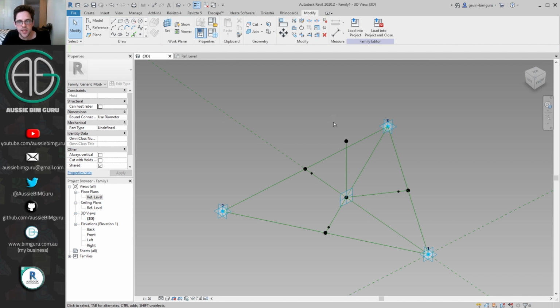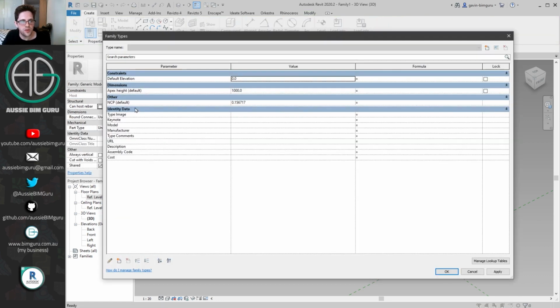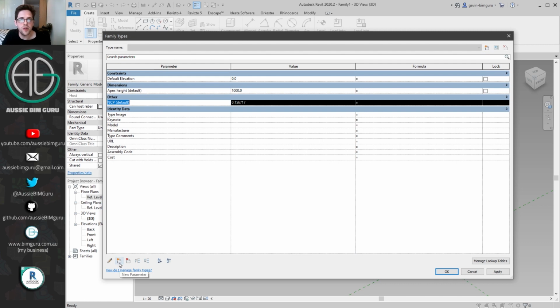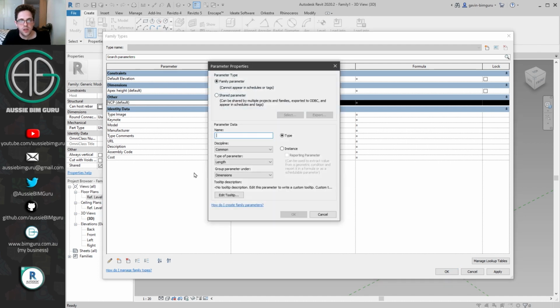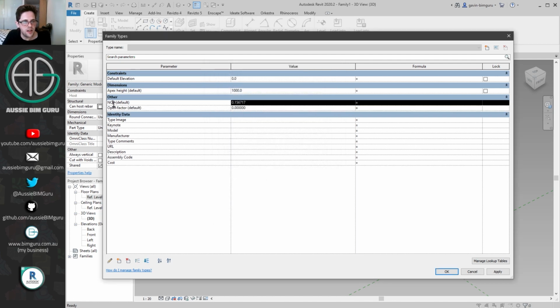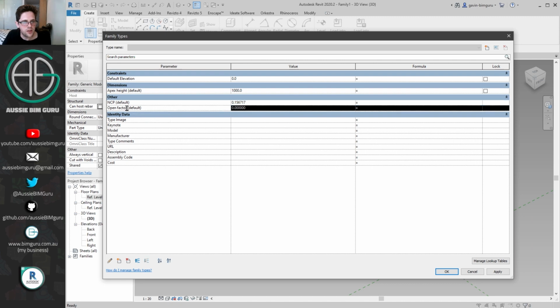Now the first thing we might do is actually just establish the formula that controls this inset and this offset. So what we're going to need for this is a number that's going to control that relationship. And this will also be the number that we're going to use to control the aperture of the panel using computational software. I'm going to make a new parameter, and I'm just going to call this the open factor of the panel. So how open is that panel? I'm going to make it instance-based, and I'm going to make it a number. Now in this case, I'm going to say that the normalized curve parameter is obviously going to be equal between 0 and 1, but like I said, I never want to quite fully close or fully open the panel.